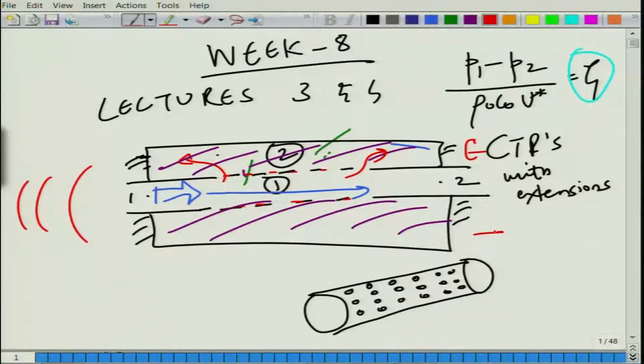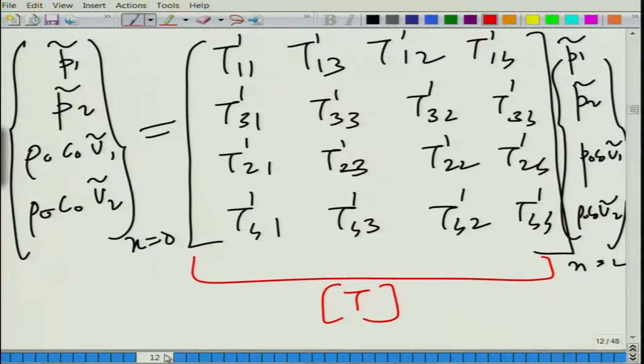But those are still advanced topics and we probably would not be bothered about that. My purpose of introducing this was that in real life imposing this rigid condition is only an approximation, because plates can sort of vibrate, they will yield no matter how thick you make them. But for our purpose we will introduce a rigid wall boundary condition there.